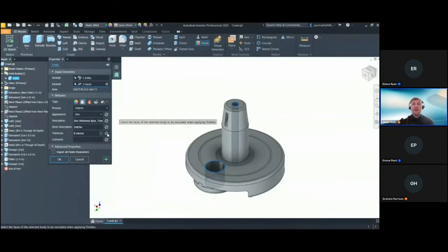What we've also got is the option to disable parameters. You'll see next to the parameters down this right hand side, you've got some disable buttons. Previously, when you exported a parameter in the finish command, it exported it into your parameters dialog box with all of these properties included. Now, each of the different types has different properties available. So what they've done now is they've essentially disabled the option so that if you don't necessarily want to pull through the comments or the description, you're not clogging up your parameters. You're only pulling through the relevant data that you want to. And you'll also see there's an option now to export all of the finished parameters within there.